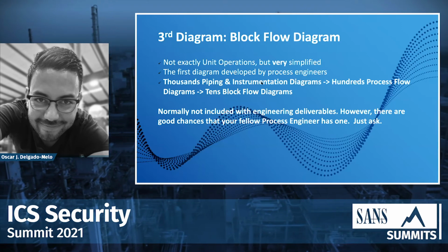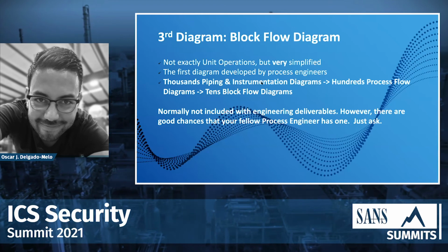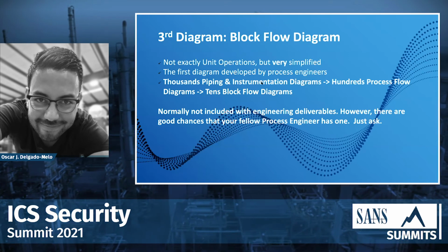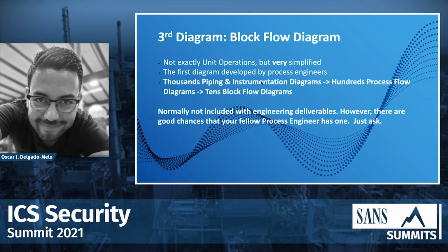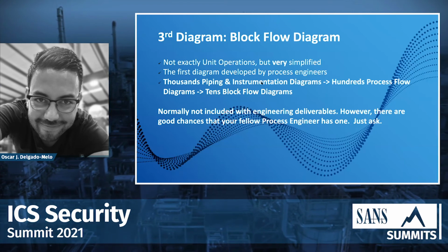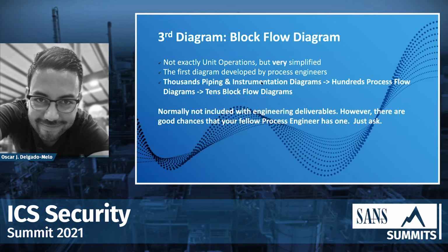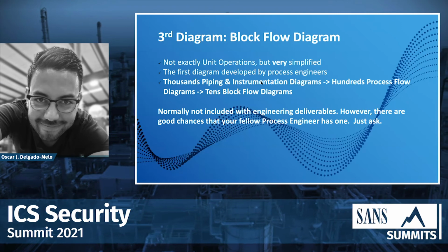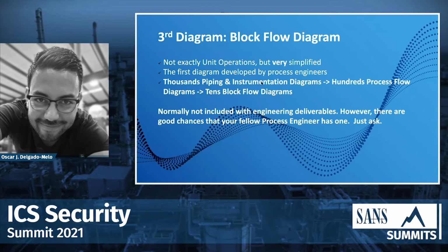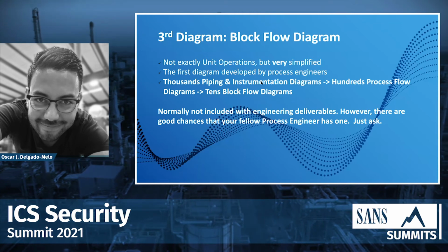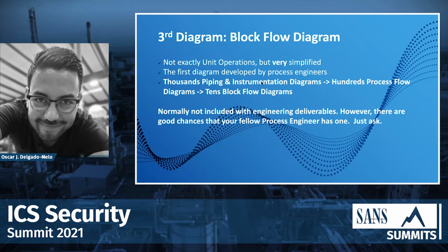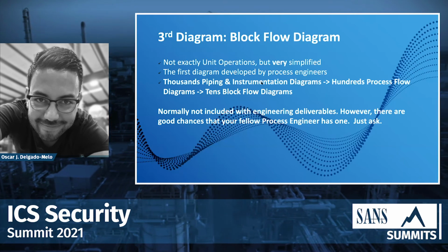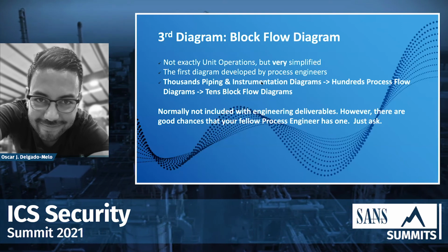Here I put an example: there could be thousands of piping and instrumentation diagrams and hundreds of process flow diagrams, but there are just a few block flow diagrams. And this is something that I have experienced in my day-to-day job. Normally this is not included with the engineering deliverables, but it's there. If you ask process engineers, there is a good chance that they will have it. And believe me, you will see all the other documents with different eyes if you start by looking at this block flow diagram and the big picture.